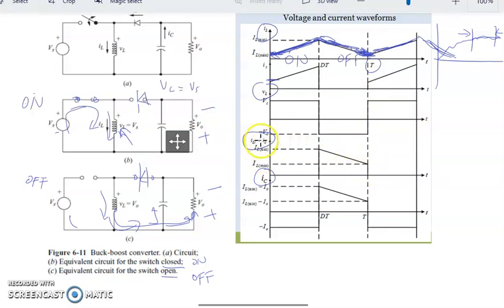And from the diode point of view, during the positive cycle the diode is open circuit, so there is no current flowing inside our diode. And during negative cycles, there will be a maximum current, as we measure here. So the maximum value here, and here are all the same. So IL max happens inside our diode, and it ramps down to the IL minimum. And when the next cycle starts, it is reverse biased, no more current flows through, so it turns to 0.